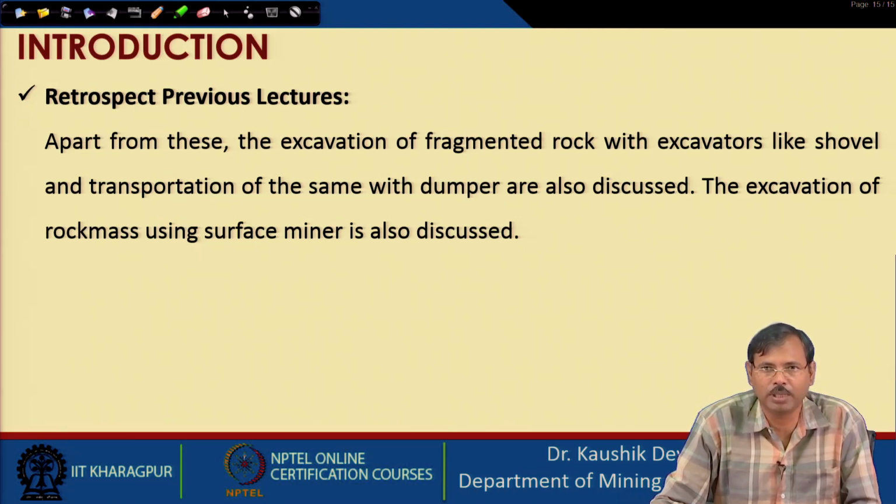Then on filling the bucket, the machine hoists up the bucket with the hoisting rope. By that time the machine starts rotating towards the dump direction, and there the hoisting rope and drag rope position themselves in such a way that the bucket is discharged from the mouth itself and the material is dropped onto the dump.